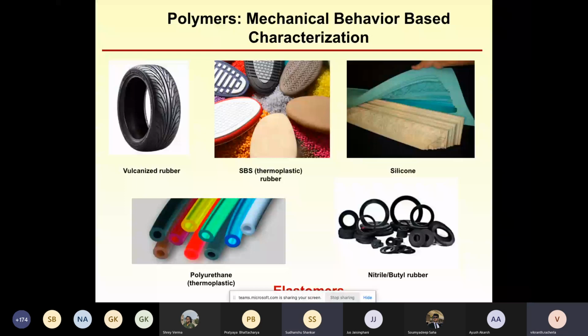So because they can deform and take the empty gaps. Very good. Because they are so soft that when you apply pressure on them, they spread out and occupy whatever space is there between the two members. Okay. So even if you take an automobile, let's say a car, you would see that between the car door and the frame, you have this rubber gasket.